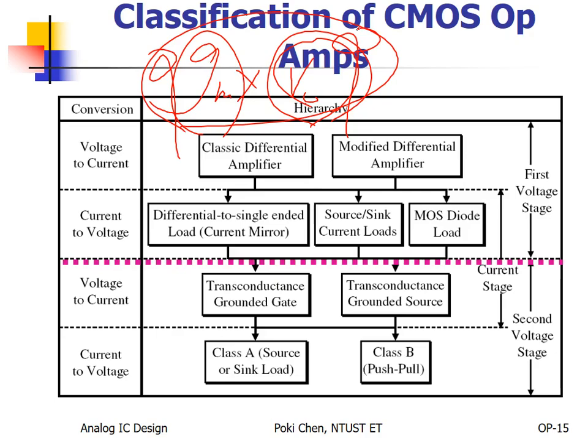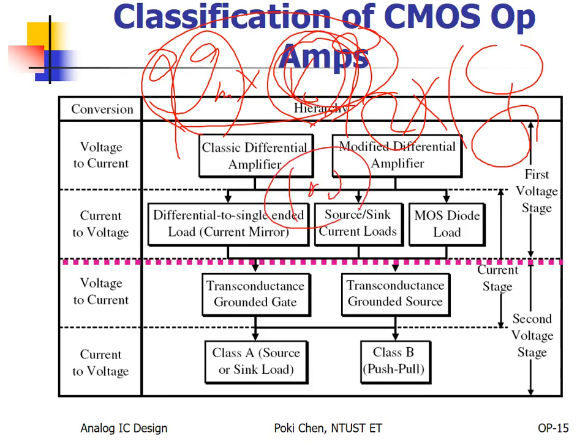But again, to increase RO, for example, by cascading, you have one transistor for output, and then above it, another cascading transistor. Congratulations, you only double the device area by 2. But how much can you increase RO? 100, 2 orders. I told you already. By cascading, we can increase the output resistance by 2 orders. That is really powerful. However, nothing is free. You need to pay for it. Pay what? Headroom. Exactly.